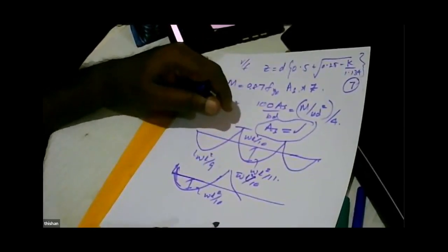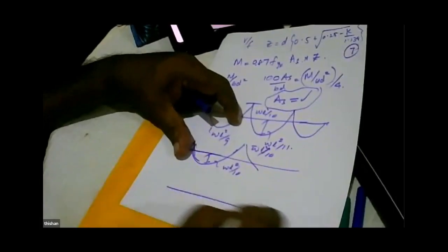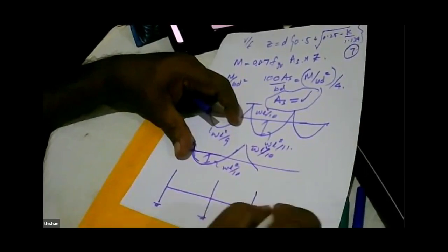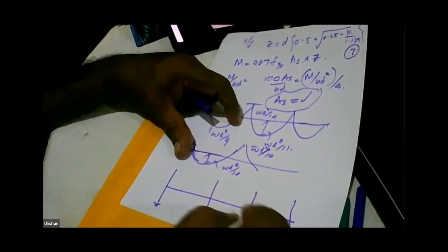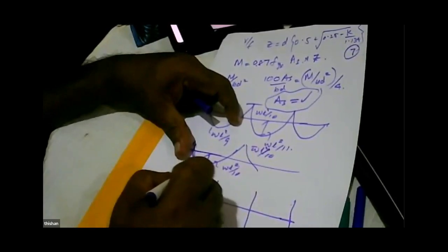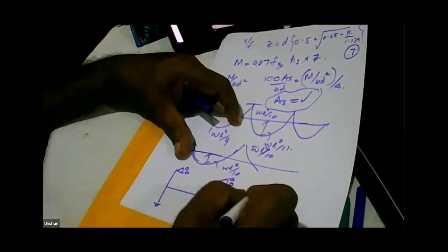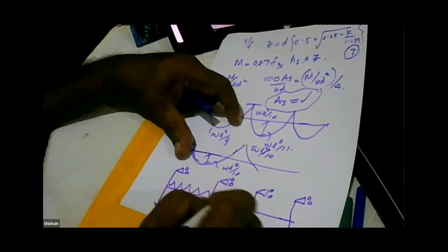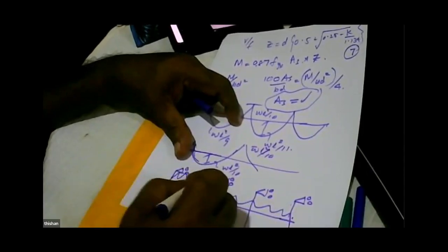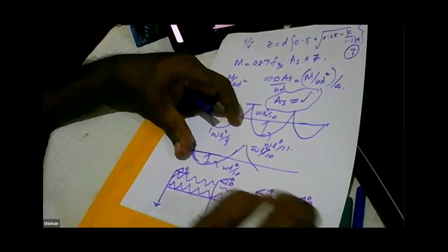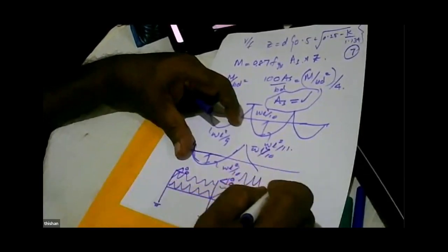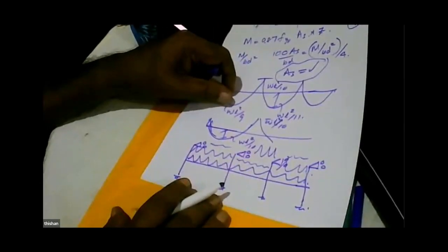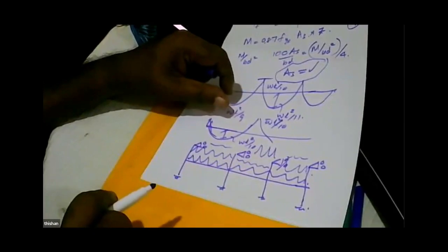On the other hand, if I want to find the moment, this is what I do. I don't worry about the full structure. I'll go for a substructure and put it onto SAP 2000 or Midas Gen. I'll put rollers here, and create this, this, and this. And then find the bending moment diagram. And then I can do wonders.